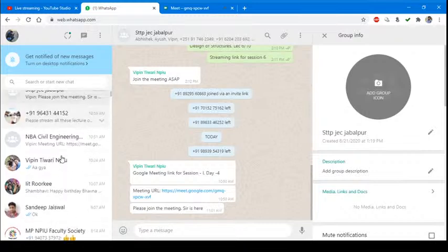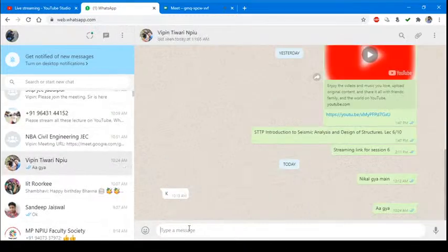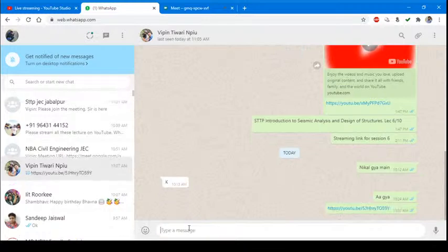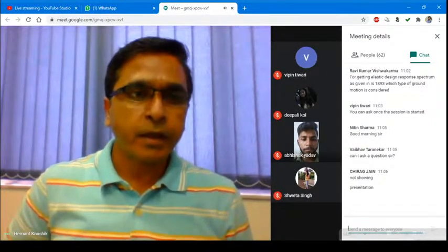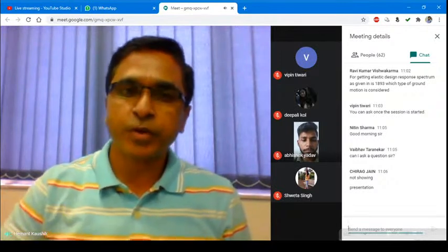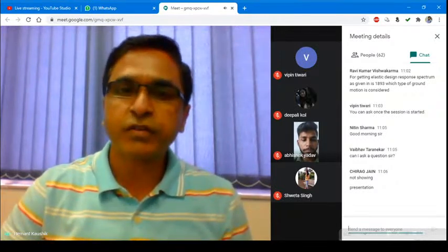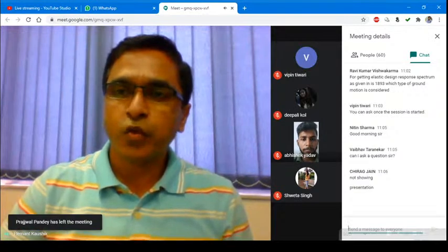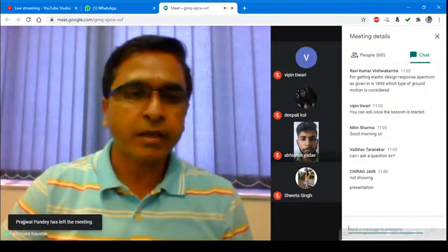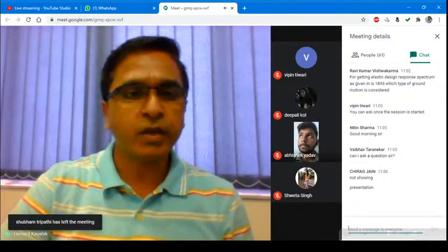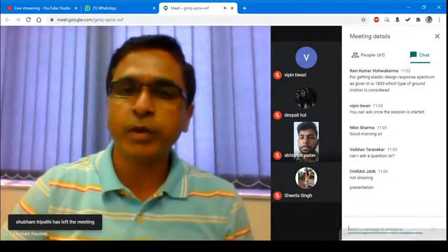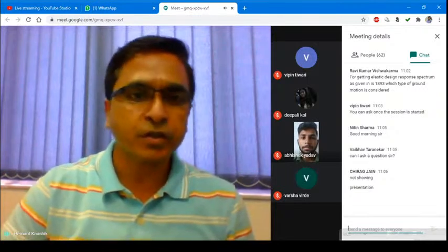But there is an earthquake, the 1952 Kern County earthquake, also called the Taft earthquake. If you develop the response spectrum for 5% damping for this Taft earthquake, you will get a very similar response spectrum to what our IS 1893 has. That is why you will find that in many studies people use this Taft ground motion.